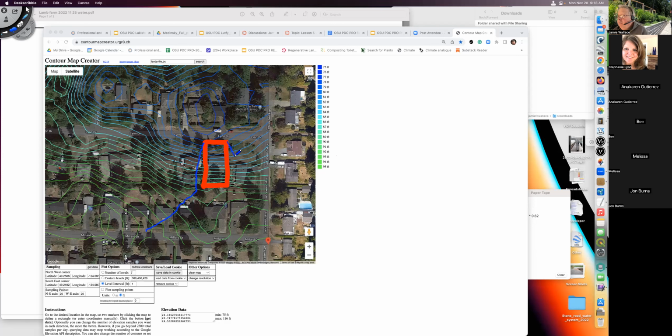We can do the same thing. And this is not exact. I'm not being completely precise with this. If I was doing this for the assignment, I probably would, but we're just making sure that this direction of flow is 90 degrees to the contour as it's going downhill. So I'm going uphill, so I kind of have to keep that in mind as I'm going up. And this looks like a bit of a tricky area there. So we've done both sides, and then we can actually just join these.